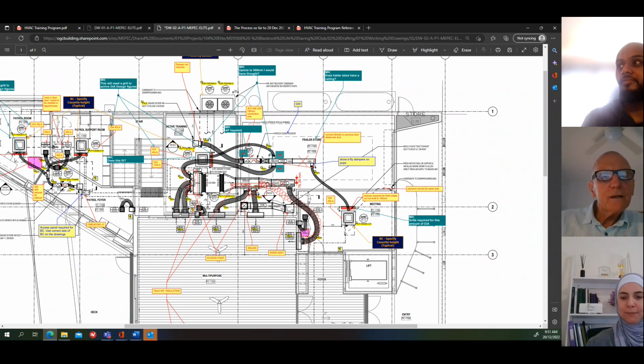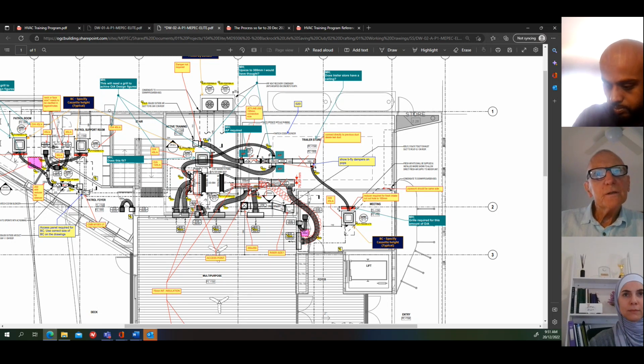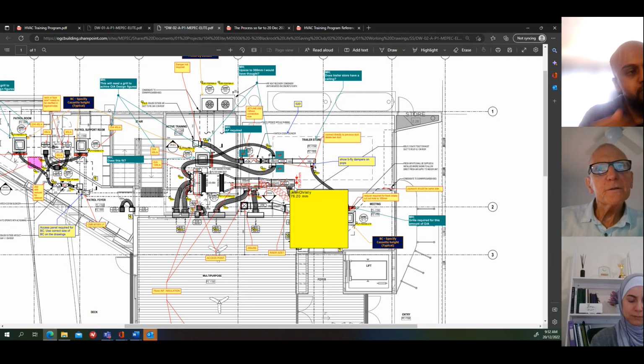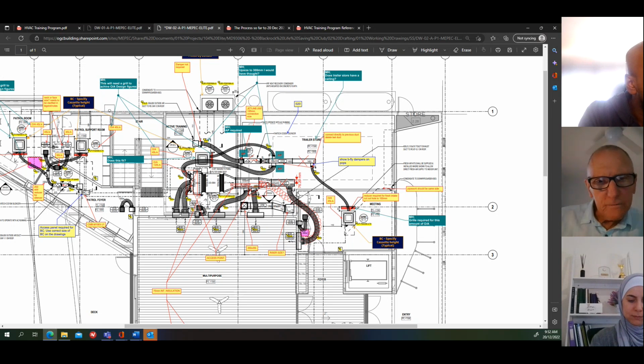Sorry, you're back. We're just talking about the next piece, which was a transition that has a certain length. It's ET, which means equal taper, so it's sloping the same on each side. It's also changed in height because it's gone from 450 high there to 400 there. Okay, so that's just a little bit of information about reading drawings. And that last piece there, the 400 by 400, is again 1400 long.